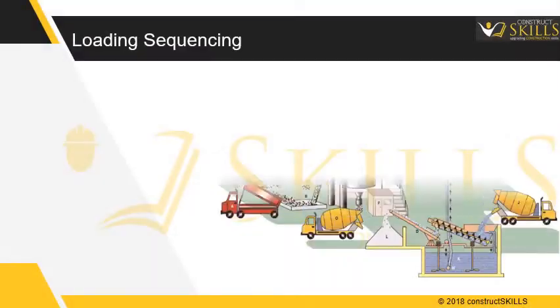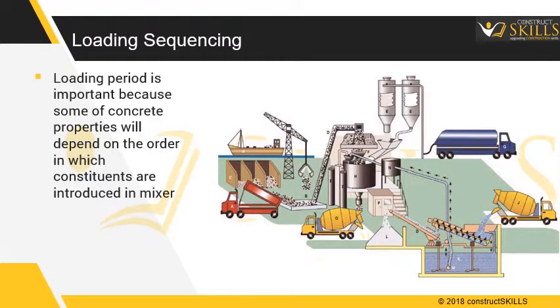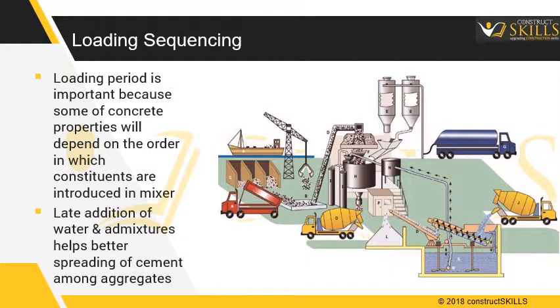Loading sequencing. The loading period is important because some of the concrete properties will depend on the order in which the constituents are introduced in the mixer. Later addition of water and admixtures helps better spreading of the cement among aggregates.